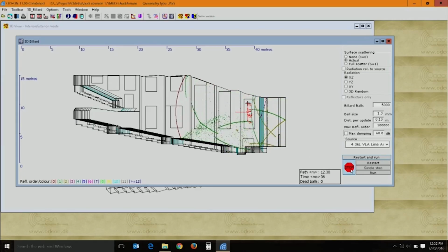I will quickly show you that. Now this is propagating. By the time it reaches probably the rear end, the direct sound is more or less in the farther end of the hall. It takes about 78 milliseconds and has travelled around 27 meters to reach the rear row. Here these are the orders of reflection, that is the number of reflections that have happened. Around 7 to 8 reflections have already happened in this area by the time you get the direct sound,